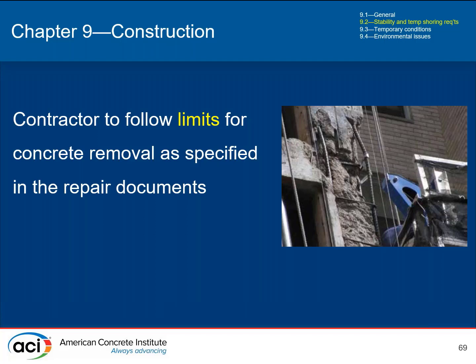Now, if you look at the picture on the right, this is a column where a lot of the concrete has been removed, and every time I look at that, I get a little bit scared because I can see that the bar on the right is engaged by the ties, but on the inside, it's not being held in position by the concrete.